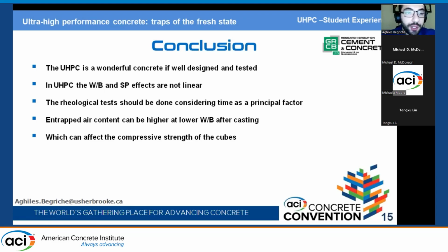The rheological test should be done considering time as a principal factor. The entrapped air content can be higher at lower water to binder ratio after casting, which can strongly affect the compressive strength of the cubes, especially during a comparison between different mixtures.